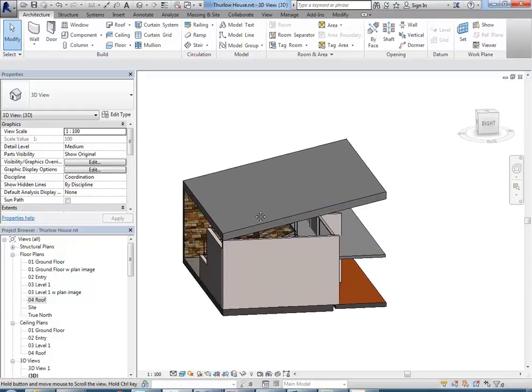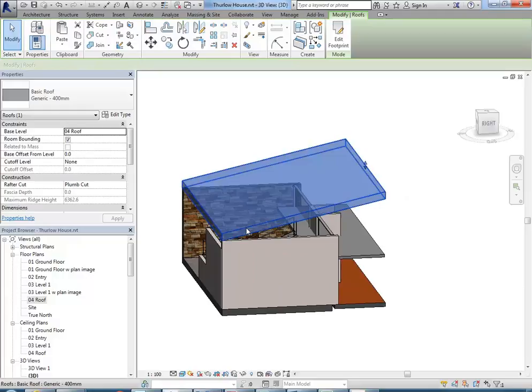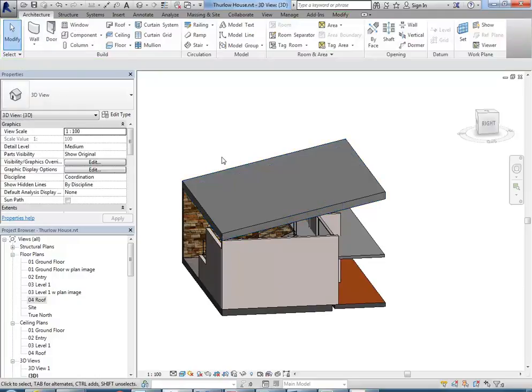Now it's a bit thick, so I'm going to do that too. You've got to tick define slope to turn it back on. That's it. And you want to make sure that line, they should all be on the outside, so you can just drag that line afterwards, just press enter, and then drag the line to the bottom of your wall.